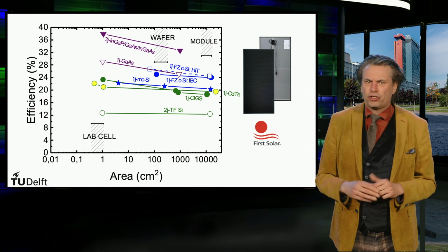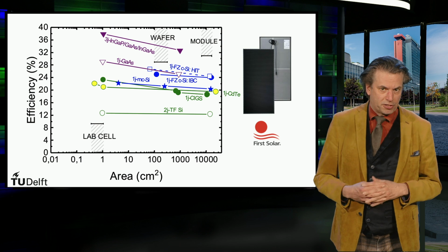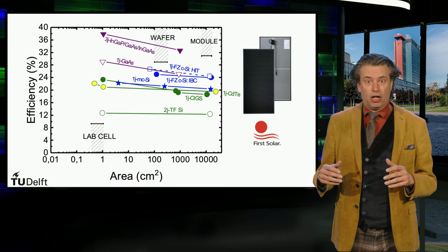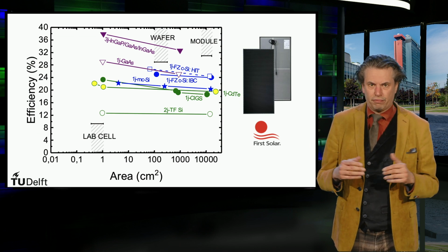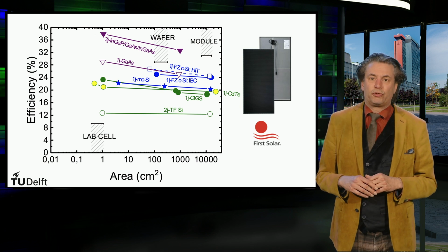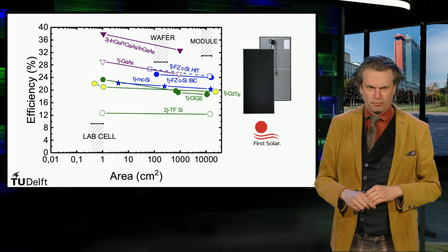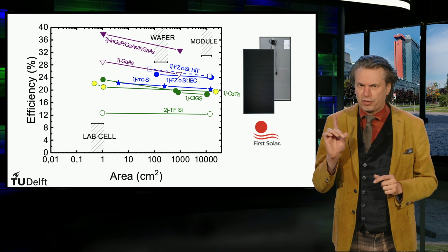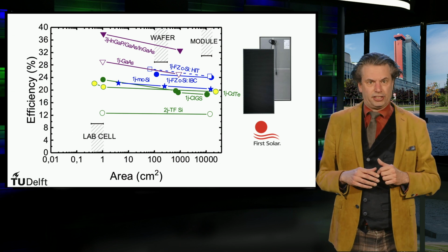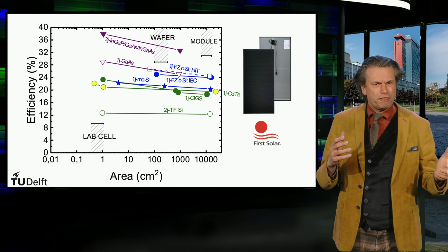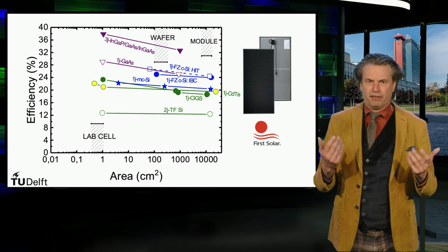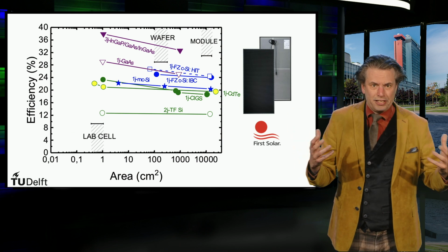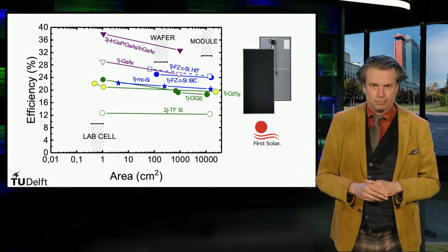The CIGS technology shows a 23.35% record efficiency for a cell of about 1 square centimeter, while Solar Frontier has demonstrated module efficiencies of about 18.6% with a size of about 1 square meter. This still shows a significant drop of about 4.8%. An important factor that plays a role is that the various CIGS module manufacturers use different CIGS processing methods. Therefore, the intellectual property needed to reduce the upscaling losses has to be mainly developed in-house at the company.